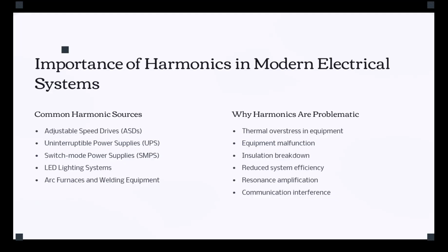during the operation. Now, those harmonics also can lead to insulation breakdown in a variety of equipment. So it's not just one or two equipment or a specific equipment. Why that happens is because one reason is the temperature rise, the extra heat that the harmonics cause in the equipment. So that would damage the insulation. But another factor is the extra voltage or current stress applied to those insulation. So they could get damaged. And if they are damaged, basically it could cause short circuits or failures.